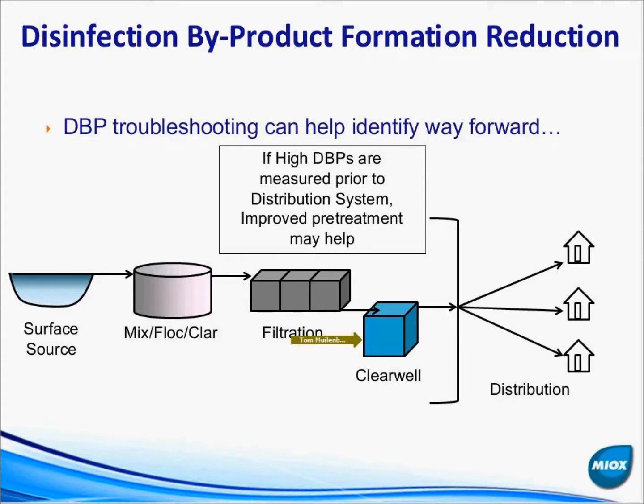Then to a clear well, and this is normally where you're doing a couple of things. One, you are maybe adjusting your pH to give you a nice pH out in the distribution system that's unlikely to corrode. You might be looking to stabilize it in some other fashion, but most importantly, you're usually adding chlorine prior to the clear well, or this might be a storage tank, in order to give you some contact time to achieve your ideal disinfection time and concentration, also known as CT, either by regulatory or performance-wise, and you'll go ahead and put that through there and then out to the distribution system.